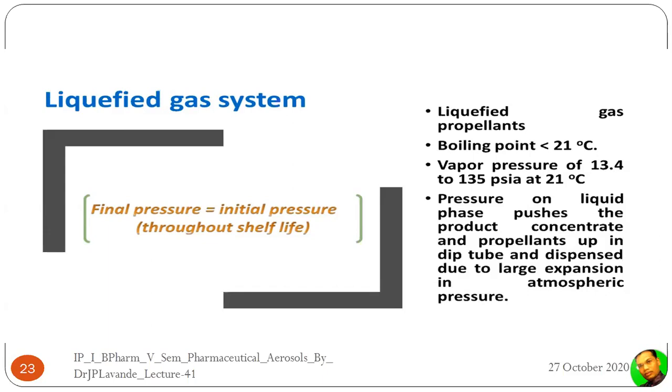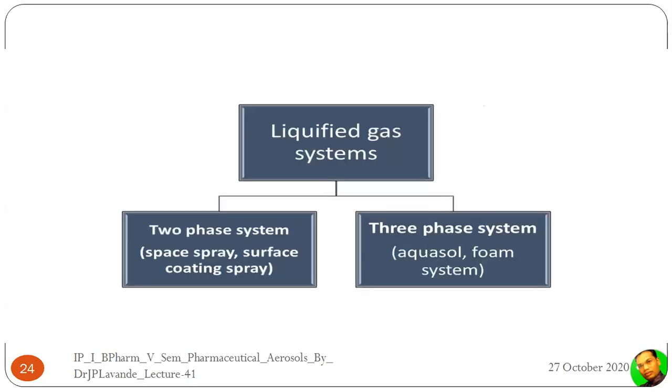Because these liquefied gas systems have a large expansion ratio, the pressure that is maintained, that is the final pressure, is equal to the initial pressure. That is the most important advantage associated with the liquefied gas system, and it helps to maintain the pressure throughout the shelf life of the aerosol system.